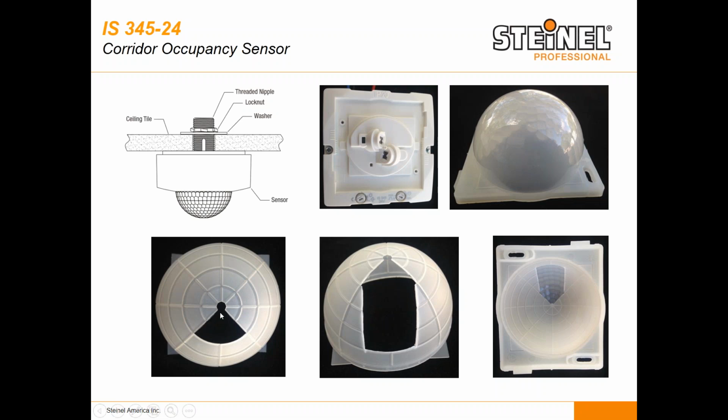And it comes with this small little triangle cut out. In a data center, it's often that you'll use it just like this, just the way that it comes. So when you have it mounted at about a 9-foot mounting height, it'll see about 15 or 20 foot down that aisle. That's often just about what you need in these aisles, especially whenever they're divided up into smaller sections.